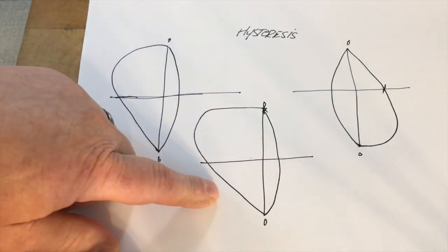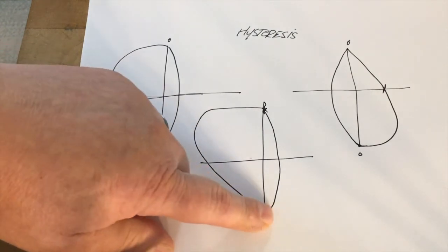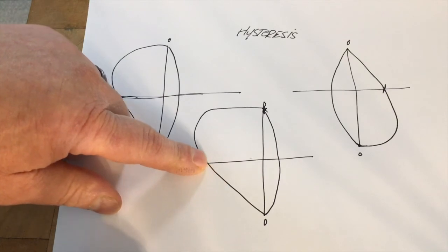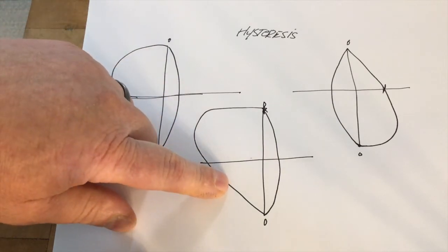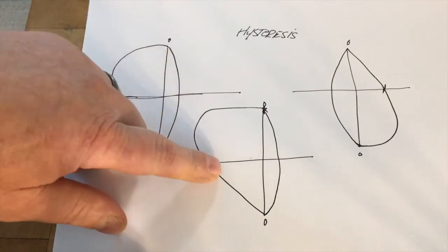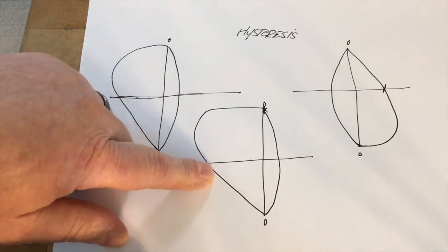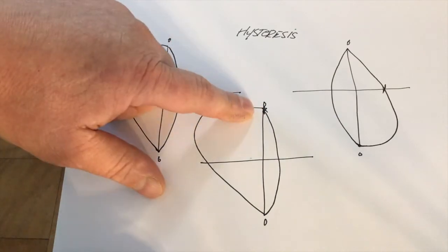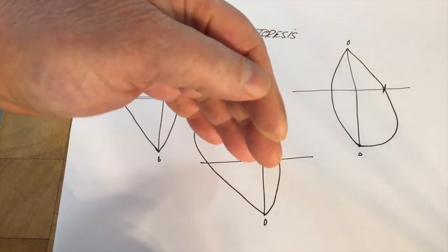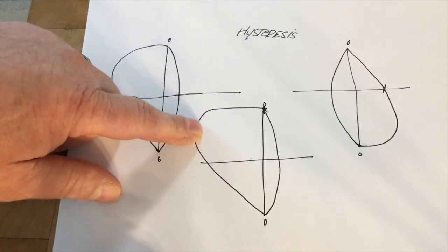And what happens is you'll hit a rebound cycle, and you'll get your rebound open, you get your rebound closed, and you'll start blocking off that bleed in that right front with the adjuster or something to get that right front, I guess, to tie down, and you'd get a real instant snapping. And this is hysteresis basically, because you're not allowing that shaft to close at the same rate it opens.